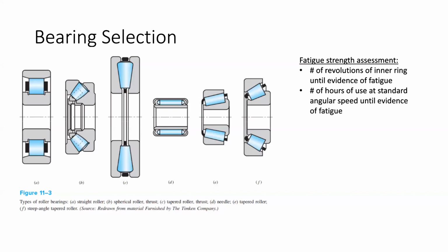So this is really how bearings behave as well, right? If I were to take a radial load on this bearing and push down on this element, even if it's spinning, in general, if I have a larger area of contact, it's going to be stiffer, right? So these different types of bearings just have different configurations that are designed to take certain types of loads.